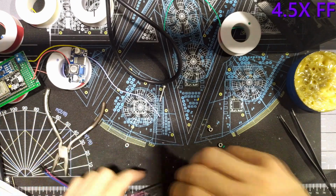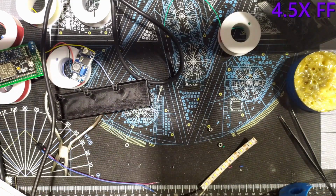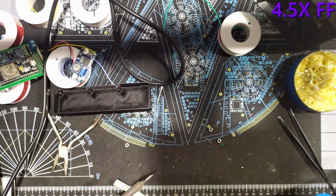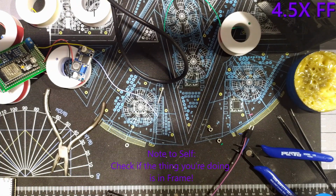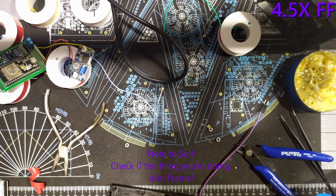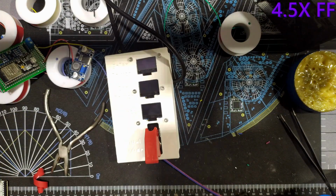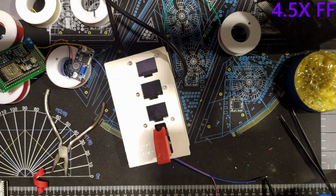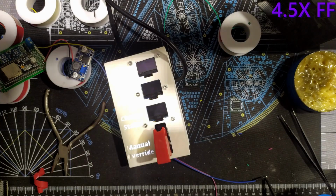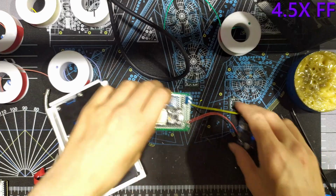Since the box did fit like a glove, I continued the assembly by soldering power wires to the cold white LED strips I selected. I then fed the wires through the small hole on the side of the box and finished screwing it on. To see how it looks, I hooked up the wires to my bench power supply and gave it 5 volts. It doesn't come across that well on camera, but it looks pretty good in person.